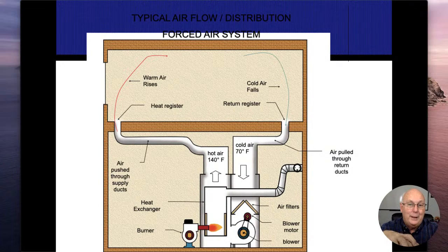I have to have my blower fan before that heat exchanger because I want to create a positive pressure on the outside of that heat exchanger, so that if I did have any openings, I'm going to lower or reduce the risk of carbon monoxide getting into my circulation air and hence coming into my house. All right. So new school, we put our radiators under the windows and we bring our return air from the outside. And then you'll see on just about every other slide that we show for forced air furnaces, it's going to be filter, fan, heat exchanger, air conditioner. All right.